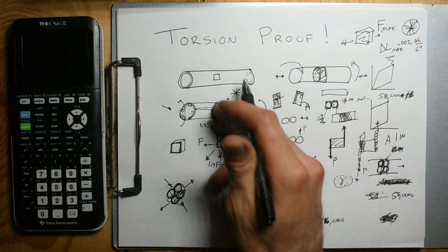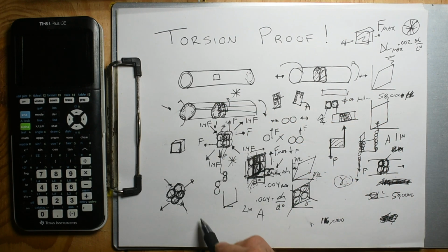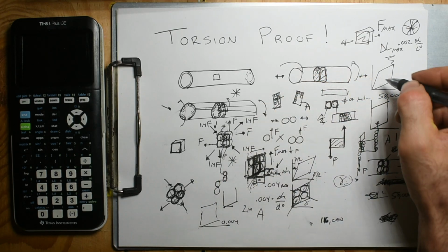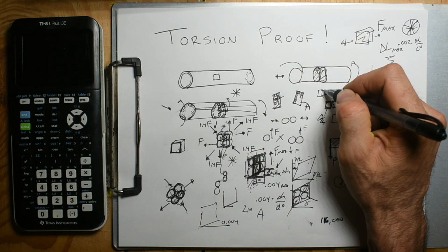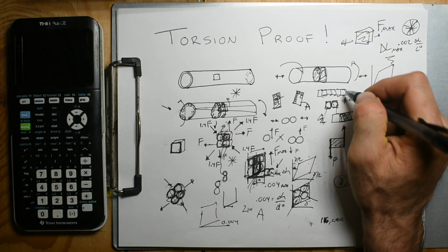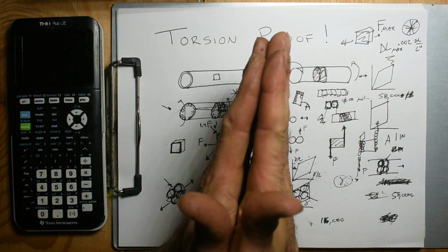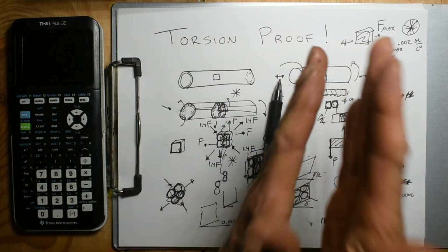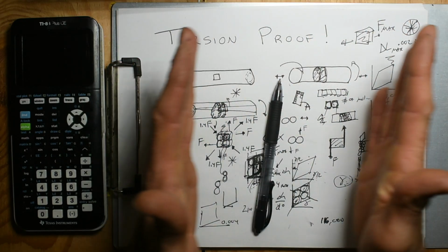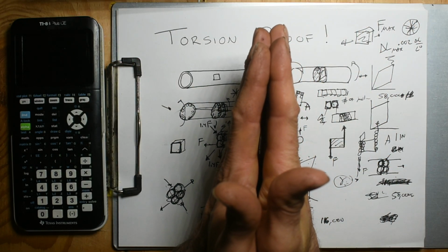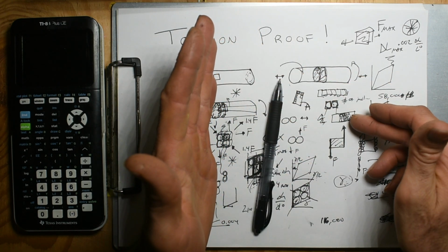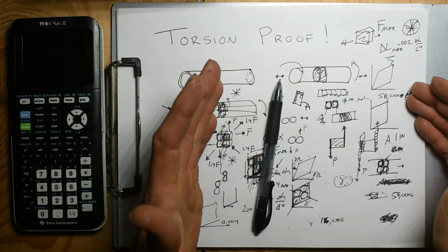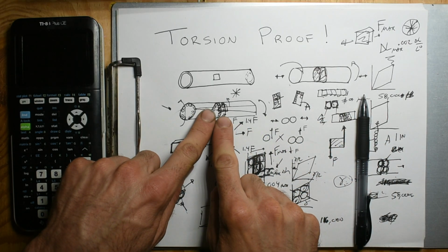Okay, so there is a max that these molecules can go. We relate that max from the angle. And for steel, this angle is 0.004. And just like we tension something, a steel bar, we have slice after slice after slice of those molecules. I mean, we have a slice of molecules, a slice of molecules, and then just on repeat, that makes up a steel bar. Each of those slices can and does and has those molecular interactions to hold that 58,000 pounds if it's a 1-inch square bar. The same thing happens with torsion.